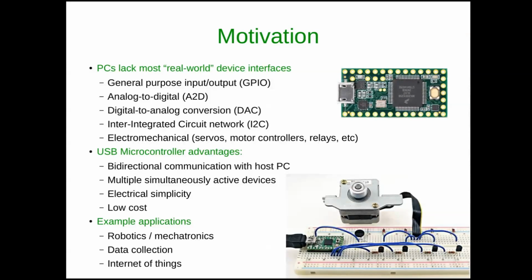Nowadays, communicating with a microcontroller is pretty simple because a lot of microcontrollers include USB interfaces. Not all of them, but many of them do. When we use USB in a microcontroller, a lot of the time we're able to actually power the microcontroller directly from the USB bus, so the microcontroller doesn't need its own battery or power supply. It also provides bidirectional communication with the host PC, and it allows us to connect multiple devices at once. So as many USB ports as I have, I can connect that many USB-enabled microcontrollers.